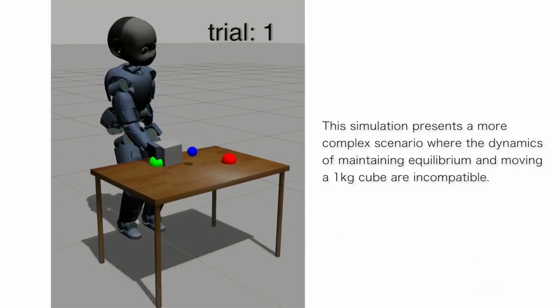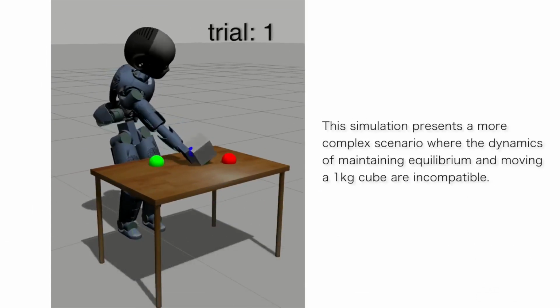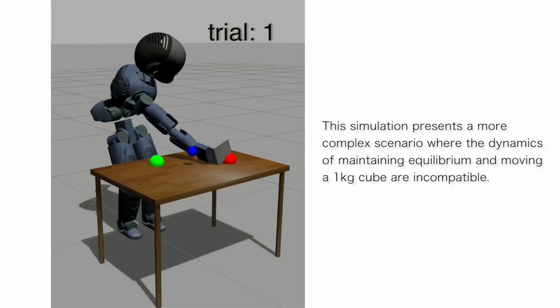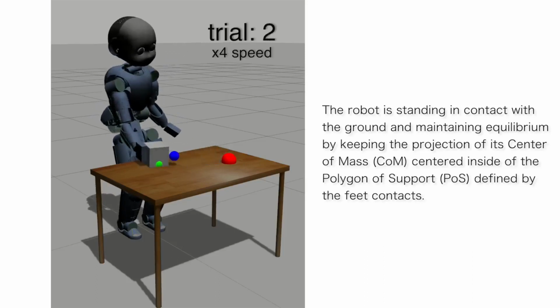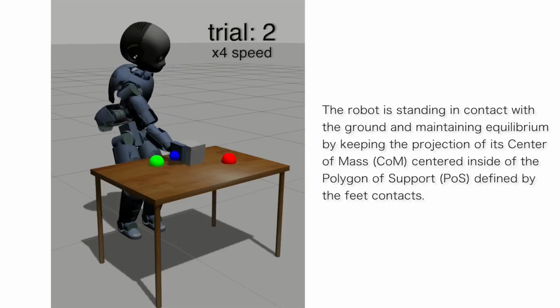This simulation presents a more complex scenario where the dynamics of maintaining equilibrium and moving a 1 kilogram cube are incompatible. The robot is standing in contact with the ground and maintaining equilibrium by keeping the projection of its center of mass centered inside the polygon of support defined by the feet contacts.